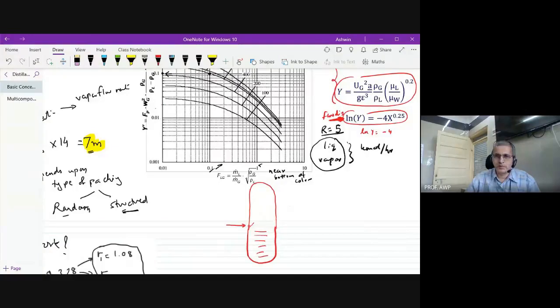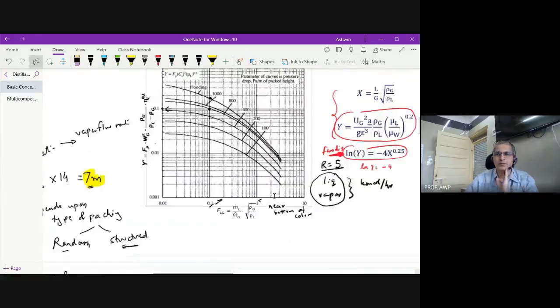Okay, sir. But yes, efficiency point of view can be important. That's why in big operations like refinery, where you have huge columns, loss of efficiency would play a part, and therefore you will necessarily fabricate two different diameters in the rectification section and stripping section. Absolutely, sir. Right. So right now we are not looking at all those issues. Right now the issue we are looking at is using this formula to calculate diameter for a given reflux ratio.